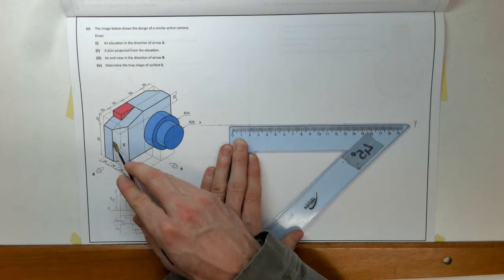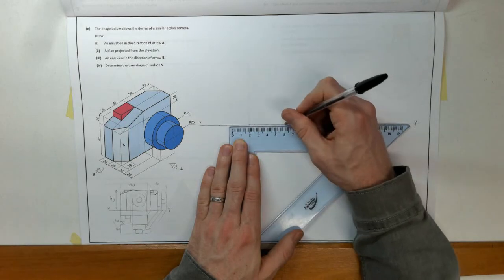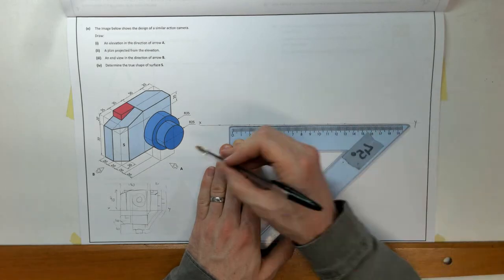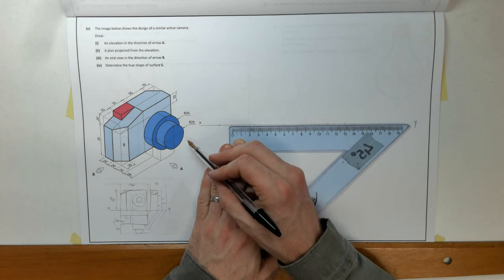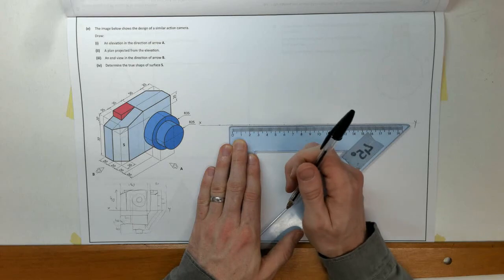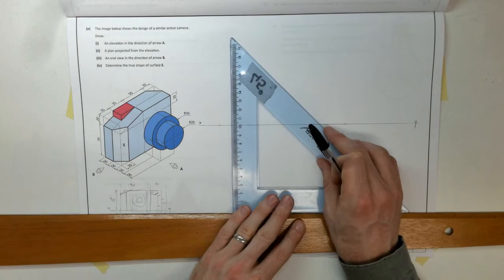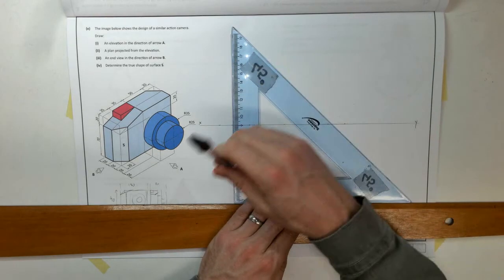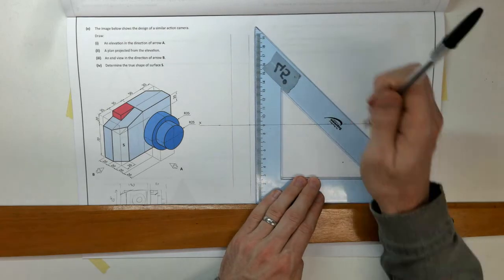Any other distances there? I've got a 25. I've got a 35. 50. Is there any other lengths? I'm going to have to find the centers of those circles also. Okay, I'll get to that in a while. Right? So let's project vertically up and down all those lengths, because I'll need them for my plan view also.